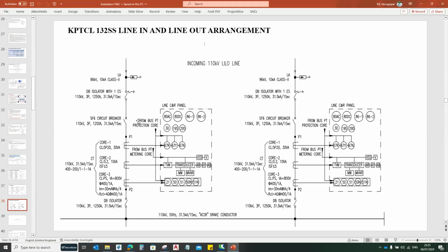And here I used the SF6 circuit breaker. Whenever the protection operates, it will trip the circuit breaker. Similarly, I'm also supervising the AC supplies as well as DC supplies in the substation. If there is a problem with the AC or DC supplies, it will give an alarm, and if the DC supply is not available, it will not allow closure of the circuit breaker. If the circuit breaker is already closed and the DC supply fails, then it will immediately trip, irrespective of the fault condition in the system.